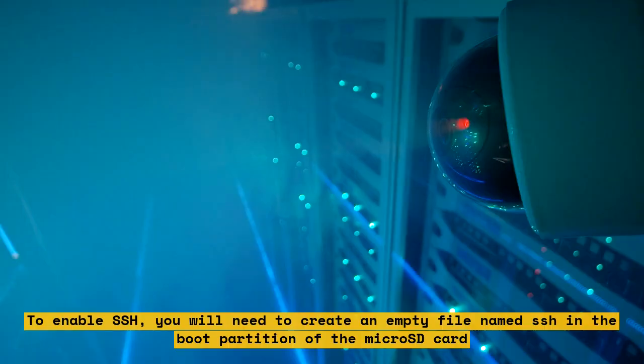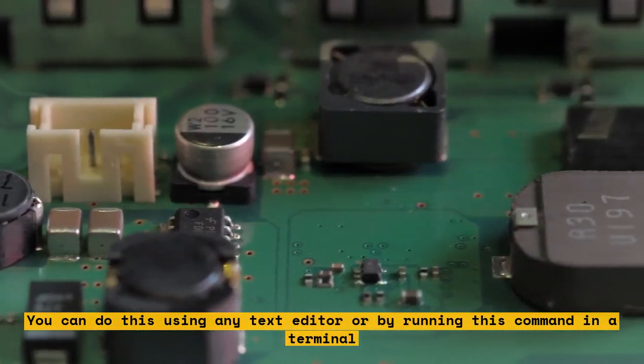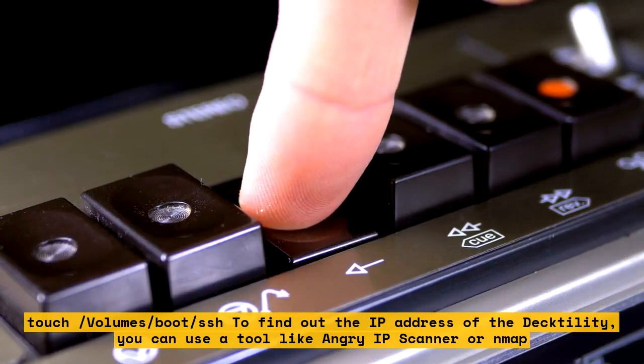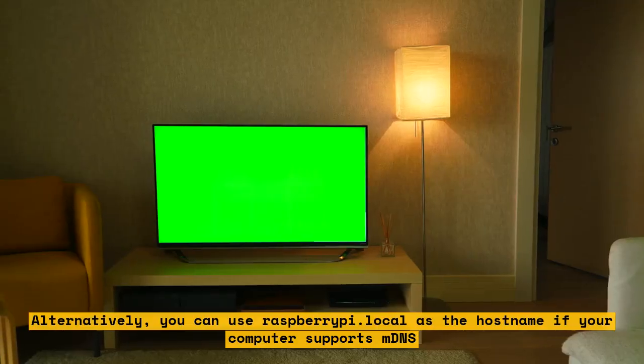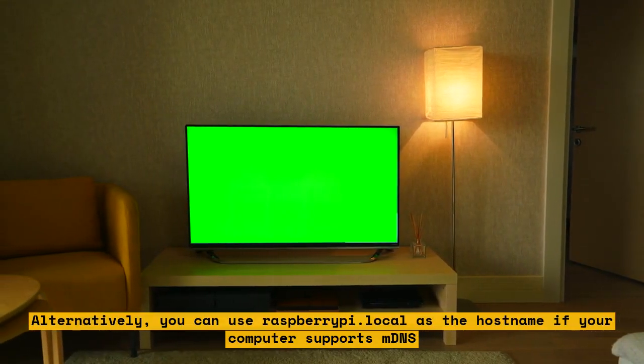To enable SSH, you will need to create an empty file named ssh in the boot partition of the micro SD card. You can do this using any text editor or by running this command in a terminal: touch /volume/boot/ssh. To find out the IP address of the Decktility, you can use a tool like Angry IP Scanner or Nmap. Alternatively, you can use raspberrypi.local as the hostname if your computer supports mDNS.